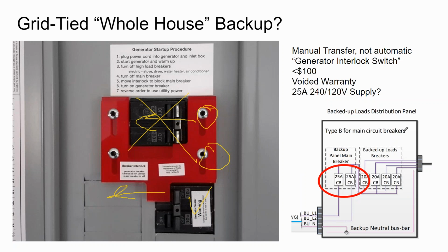Okay, well, here is the critical load panel for one of the most popular grid-tied storage solutions, which is SolarEdge. And what we can see with SolarEdge is they're outputting a leg 1, leg 2, and neutral. That's a 240 volt split phase service coming out of this SolarEdge critical load panel. And so what you could do,